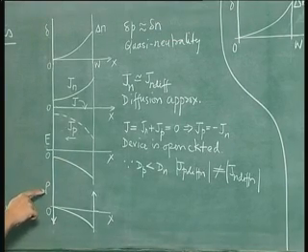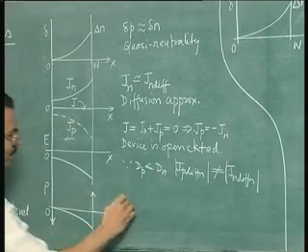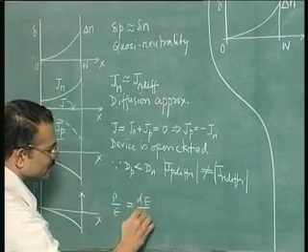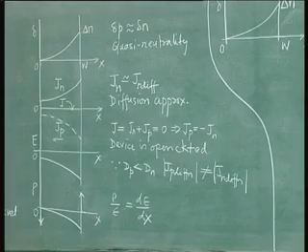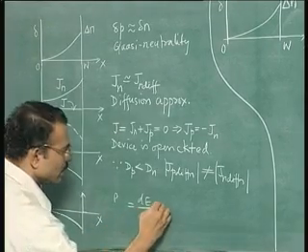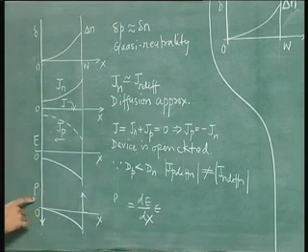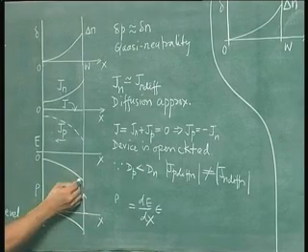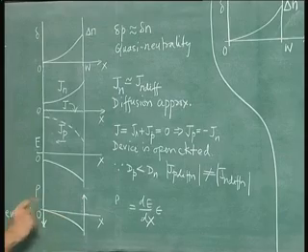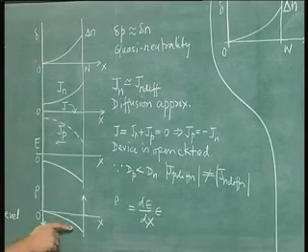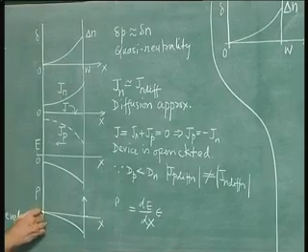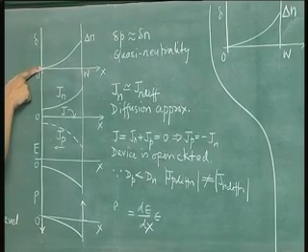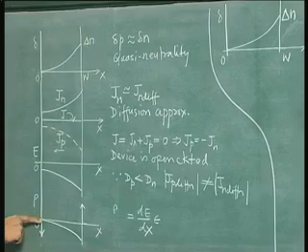Now we can readily derive the space charge distribution from the electric field distribution using Gauss's law. So Gauss's law says that rho by epsilon is equal to dE by dx. So rho is equal to dE by dx into epsilon. That is what is shown here. You take the slope of this, you get this. So rho is negative because you see the slope is negative. Then you can see that the space charge here is 0. This is because the excess carrier concentration is 0 at this point. So if excess hole and electron concentrations are 0 as shown here, obviously the space charge should be 0.